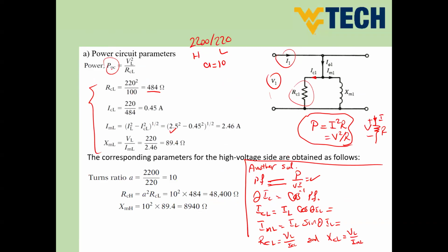So in this case, if you replace all of the relations here with the power relations, as you can see here, guys, we use the power relations to make calculations. So here, for instance, for the no load test, we use the power here, correct? So instead of that, VL should be considered, is it line or phase volt? And the value is it 3 or root 3, and consider this in all of our calculations. So this is the only difference between single phase and three phase transformer.